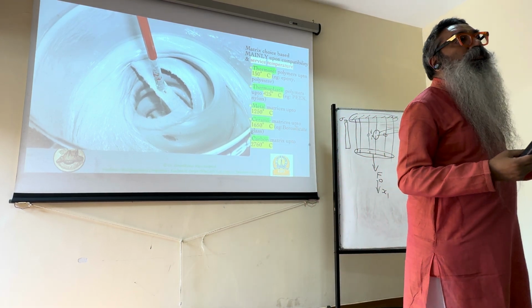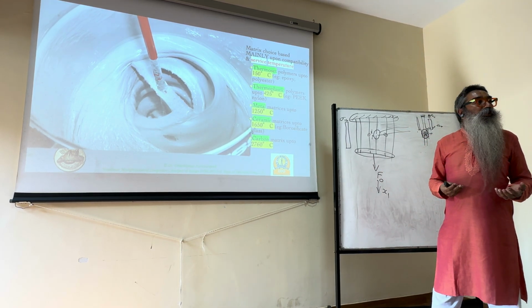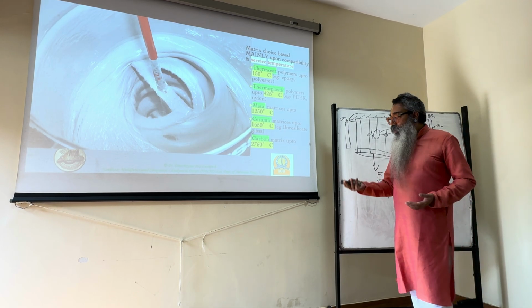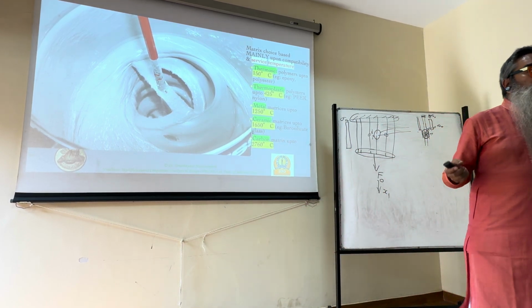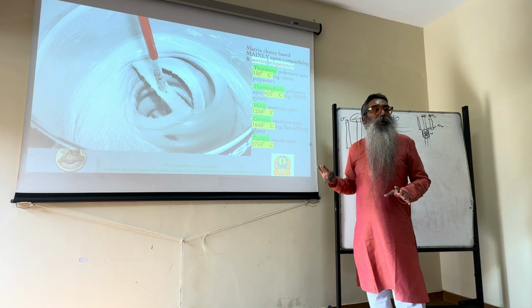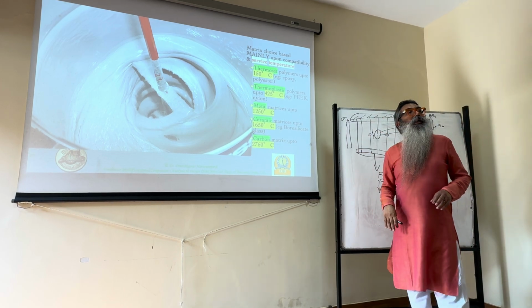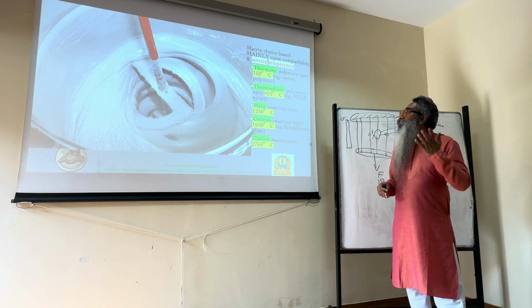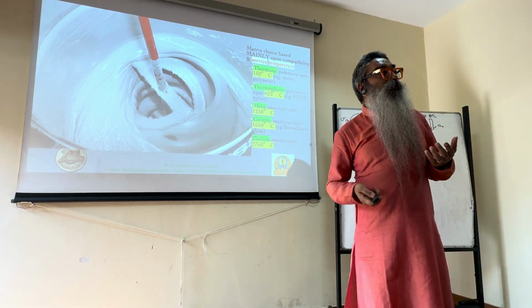As we said, there's a possibility of the polymer swelling, etc., in humidity. So you have to make sure that those are not major issues. Corrosion, especially if it's a marine environment in which it is operating, like on aircraft carriers, the naval aircraft, etc. So you have some special requirements there also. But this is more or less the generic way in which we try to understand various types of matrices depending upon the temperature the components will be exposed to during their service life, or even during the manufacture for that matter.